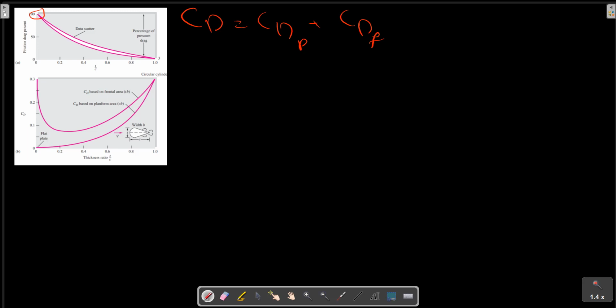At thickness equal to the chord length, simulating a circular cylinder, the friction drag is only about 3% in this case. The ratio of T on C is shown here. We have the 0 point here and the circular shape at the front of the streamlined cylinder.